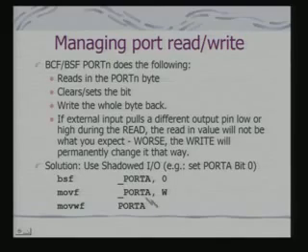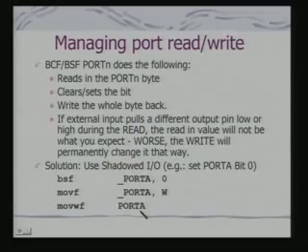And then what you do? You write onto W, and from W you write onto port A. So here what is happening is you are actually reading the data, and whatever manipulations you are doing are on a shadow register. So it's not being directly done on the port A register. The only thing is that I am writing the final result onto the port A register. So the intermediate result will not affect the operation that you are trying to do.